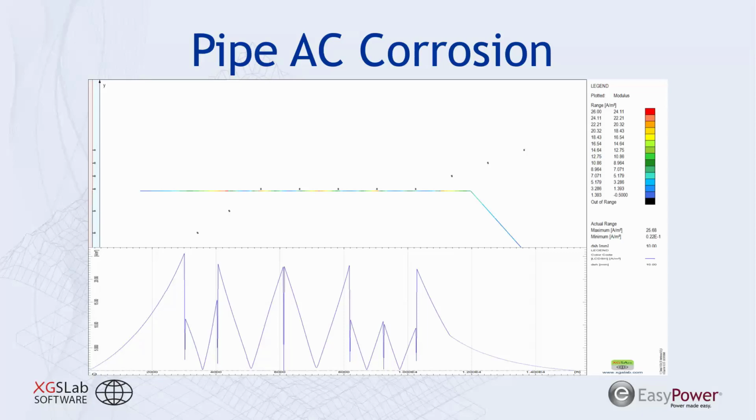And insulated joints is one of those examples where many pipelines may not be able to insert an insulated joint, as they may not be able to either disable the pipeline or the physical strength required to pass whatever the pipeline is containing. It could be a high enough pressure that there's not an insulated joint strong enough to contain that material. So grounding may be your only option in some instances, or aerial counterpoise, or some sort of other shielding.